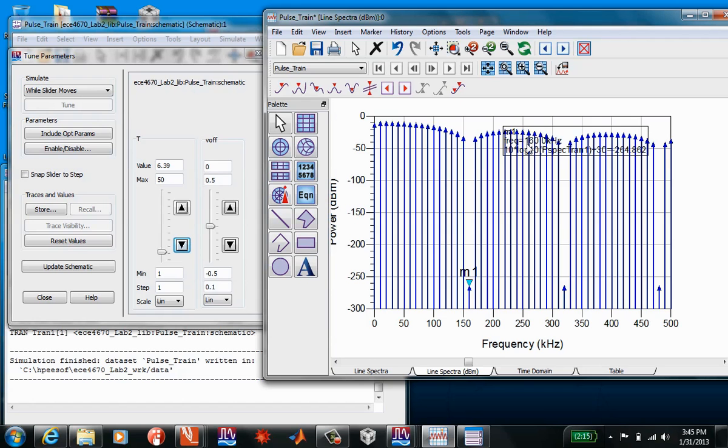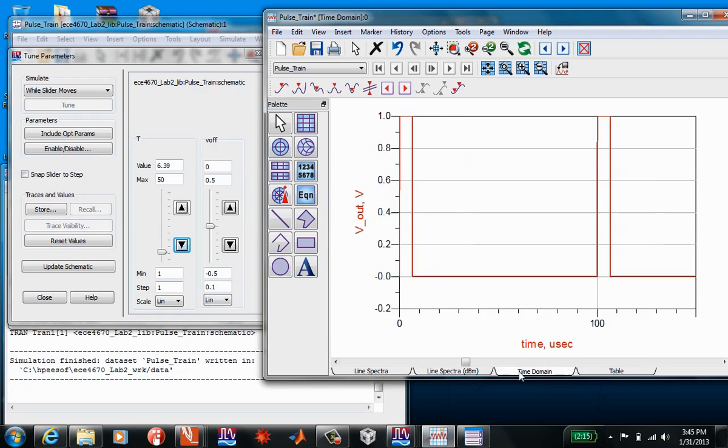So I've got something down here, now just rescaled and covered it up. That's the 16th harmonic in this case. So that must mean that the duty cycle is 16%. So this is on 16% of the time and off the rest of the time.